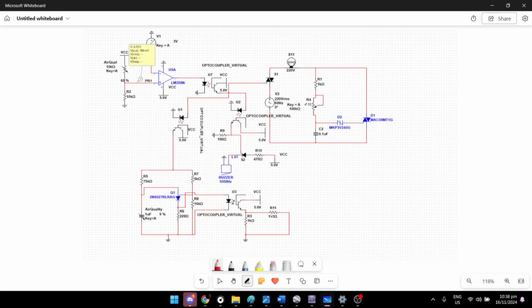Okay, so overall, we have those sensors, and this is the main sensor that will trigger everything. We can do a much more complicated approach by using more sensors. If we use more sensors, then our data is going to be much more accurate. But since this is just a demonstration, I have just used one here, but we can expand if you wanted to. We have here a comparator circuit, and that comparator circuit simply says if it's on or off for the system, and if it's on, then it triggers everything in this optocoupler range.